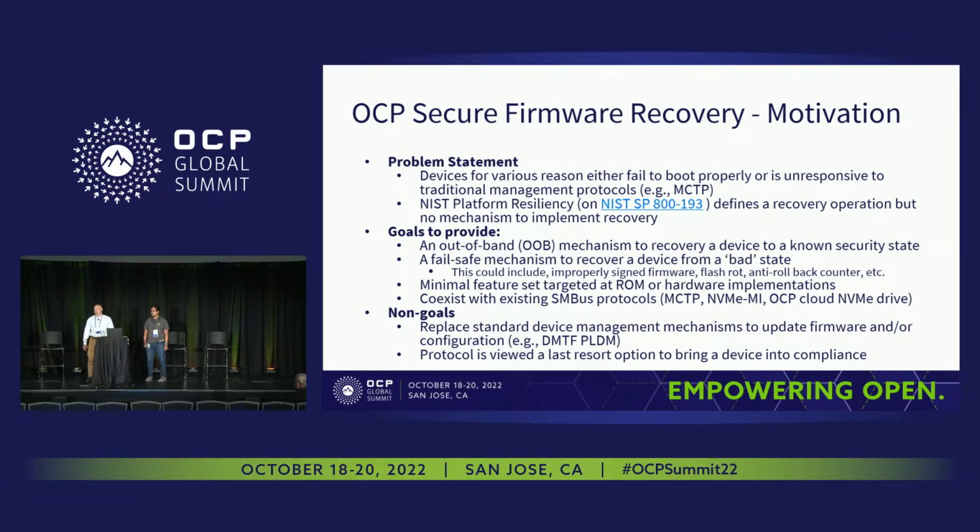We did not replicate the root of trust or any of the security pieces. One of the key pieces of this is what we call the recovery image. It passes all of the operational checks from a security perspective. So it's signed with the secure boot key and has all the anti-rollback protection. It needs to be a full production image. That was a common choice because a lot of times these old recovery images that lie around have known security vulnerabilities. You go into recovery mode and then you can attack the device.